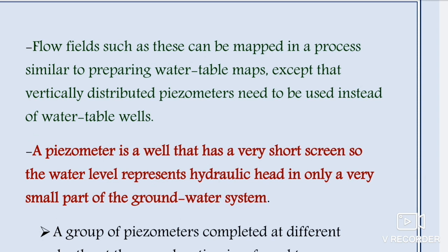And the flow fields such as these can be mapped in a process similar to preparing the water table maps, except that vertically distributed piezometers need to be used instead of the water table wells.